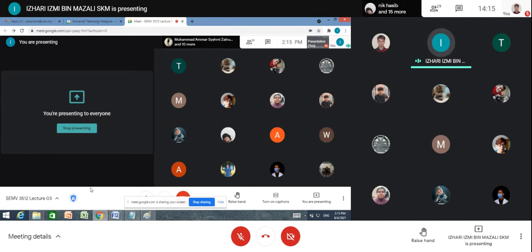Then that is the parameter you can use as your measure, to see whether your ABS is good enough or not. So that is the real example. The same with traction control. You have to look at how the traction control functions, and then based on that we define what parameter we can measure. For traction control, I am not sure how to measure it, we have to look at the details. But for ABS, I think maybe braking distance.